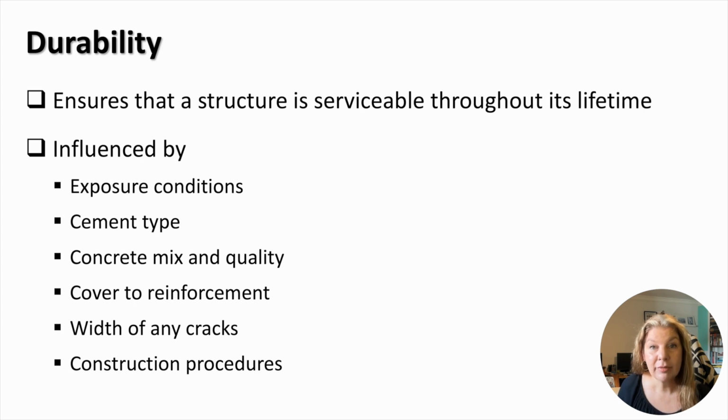The durability of reinforced concrete structures is influenced by several factors, and they include exposure conditions, cement type, concrete mix and quality, cover to the reinforcement, width of any cracks, and construction procedures. All these factors are interdependent. Let's discuss them in a bit more detail.